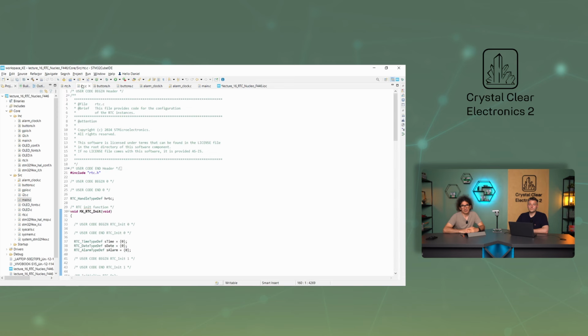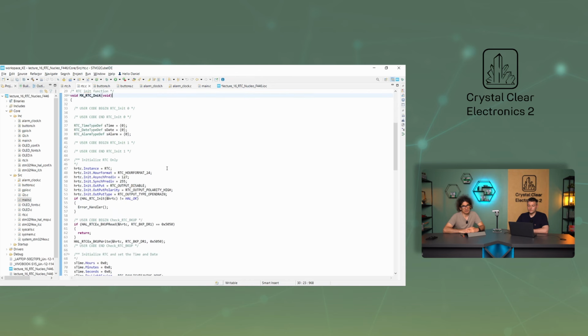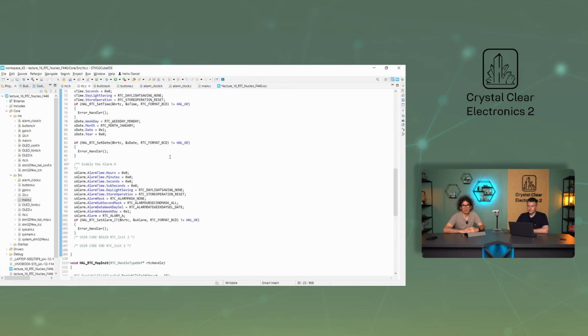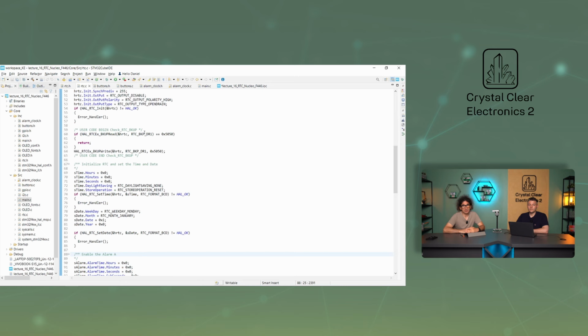The file rtc.c contains both the instantiation of the hrtc structure, declared by rtc.h, and the implementation of the MX_RTC_Init function. The code basically sets the time and date format and enables alarms on channel A in interrupt mode. There's also a handwritten section in the code lines between the comments USER CODE BEGIN CHECK_RTC_BKUP and USER CODE END CHECK_RTC_BKUP.